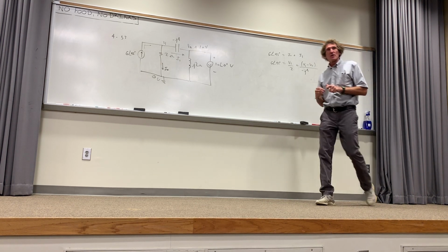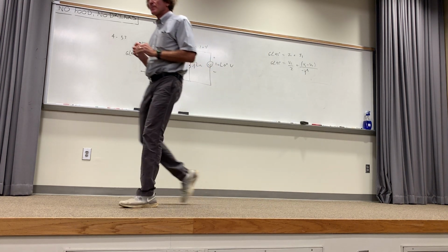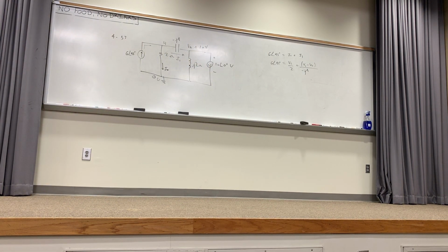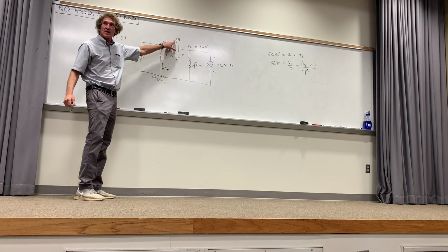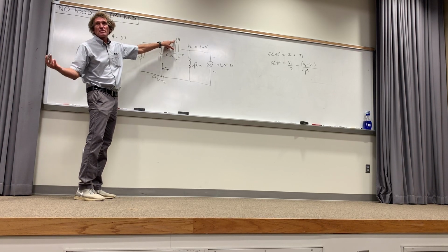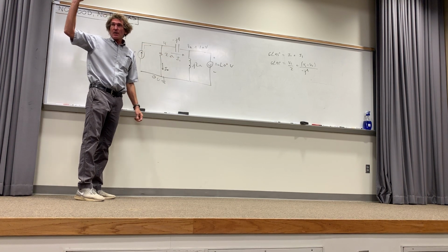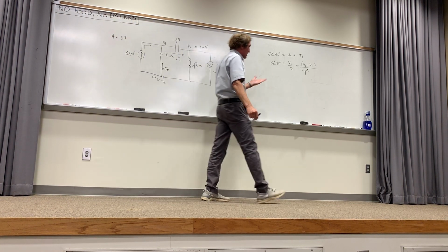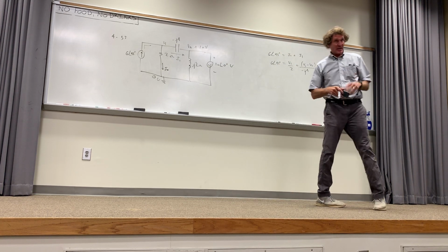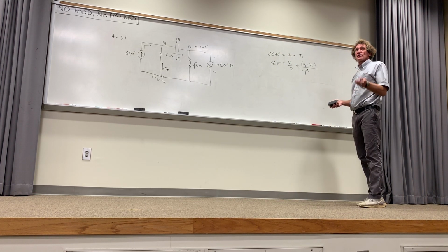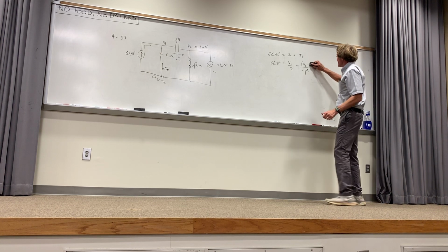I can't understand. You say V1 minus V2 is what? No, it's divided by minus J4, because that's the impedance here in ohms. You all see that, class? It's only divided by minus J4 because that's the impedance. How many see this right here? What I've done. Now, this is the equation, but what can we do with V2 right here, guys? What is V2? 10. Just put 10 in.